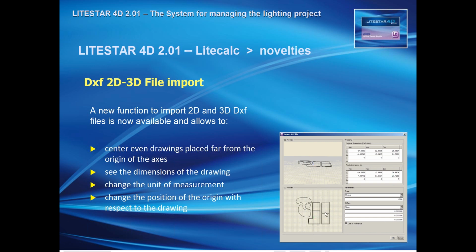With the new window, the origin will be placed down here at the left bottom of the second window, and the drawing will be shown with the little point. Through the options we have here, for example, through the offset, we can move the absolute origin and bring it close to the drawing, so that the drawing will appear in this window. It is then also possible to